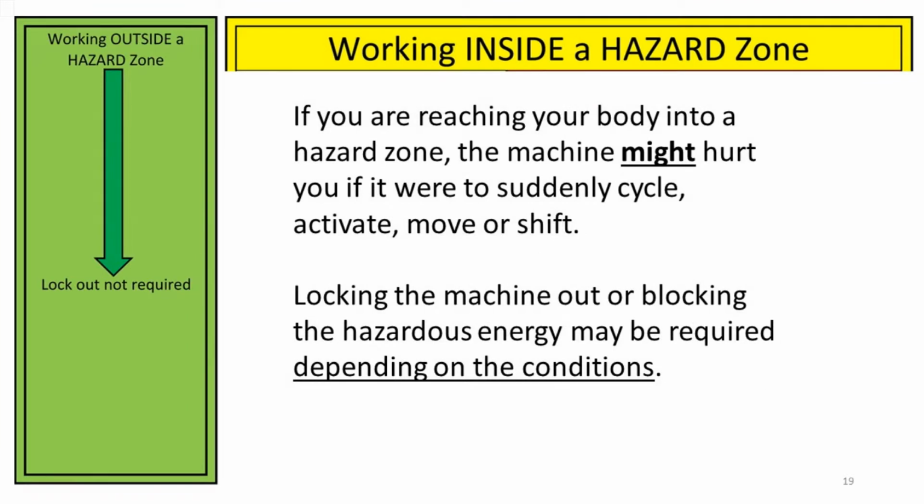If you're reaching your body into a hazard zone, the machine might hurt you if it were to suddenly start up, cycle, activate, move, or shift. Locking the machine out and or blocking the hazardous energy may be required depending on the conditions. What kind of conditions?